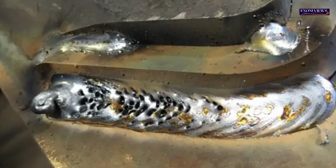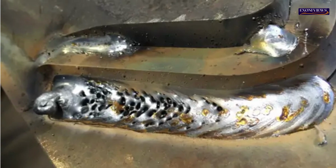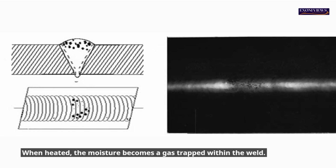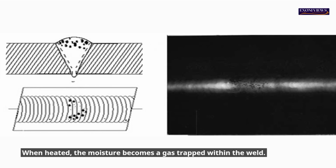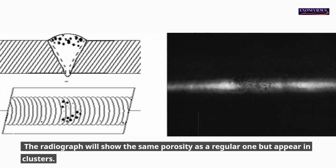Cluster porosity. Cluster porosity occurs when flux-coated electrodes become contaminated by moisture. When heated, the moisture becomes a gas trapped within the weld. The radiograph will show the same porosity as a regular one but appear in clusters.